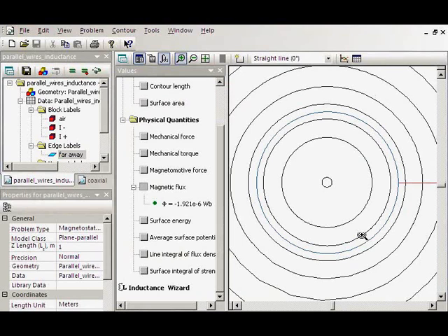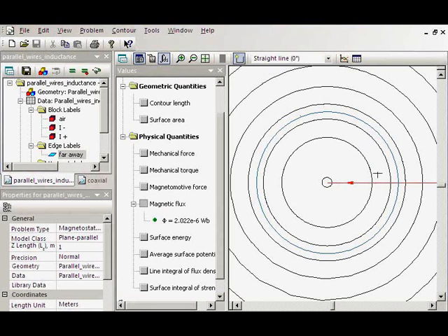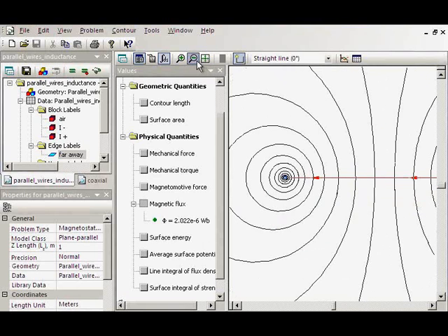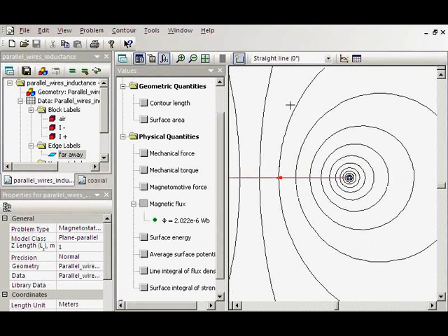There is a flux inside the conductor. And my integration contour does not include this flux. It is not calculated here, so we get smaller value. Let's correct my mistake. I will correct the contour and add small parts to my contour to calculate both external and internal flux.